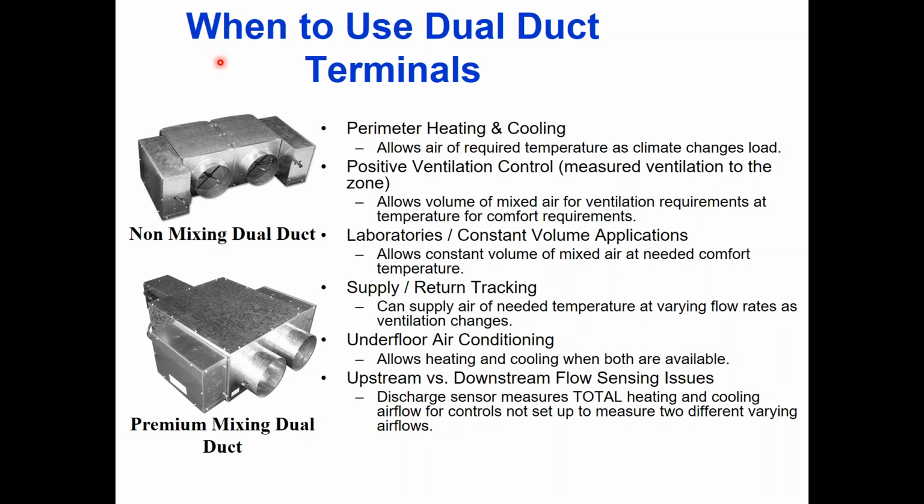It does not do a good job of mixing, so you need to have a long distance after this one on the discharge side for those two air streams to mix. The premium one is obviously more expensive because it has the word premium in it, right?